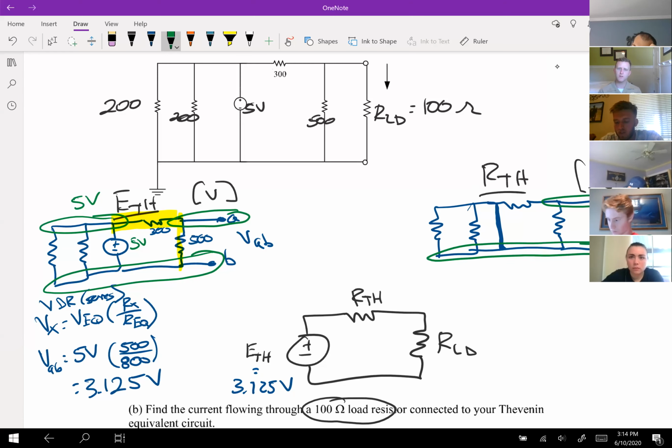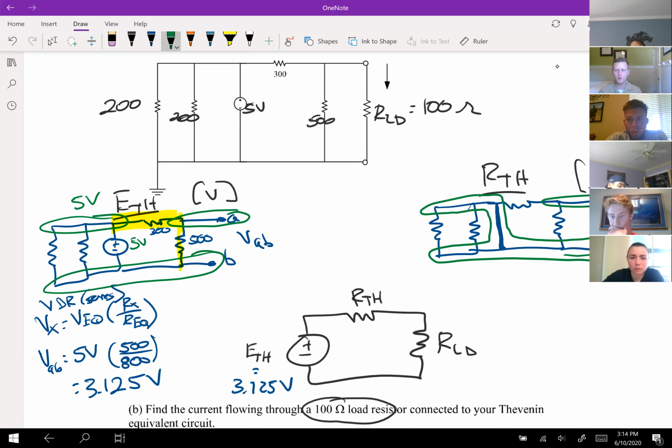Now here is what B was initially, but now that we've added in a wire, I'm going to redraw my node. I drew it there because that's probably what you're thinking of, and that works. But this is also all a part of node B, because notice there's no elements inside of that entire set, right? So that is the true node according to how we draw nodes. And so for the ohms to get from node A to node B, it is only taking the 300 in parallel with the 500.